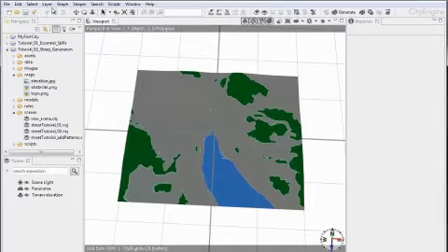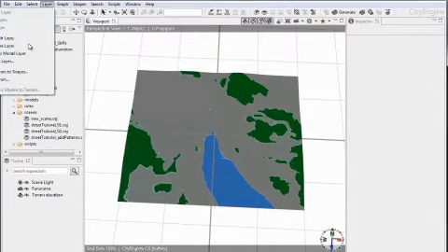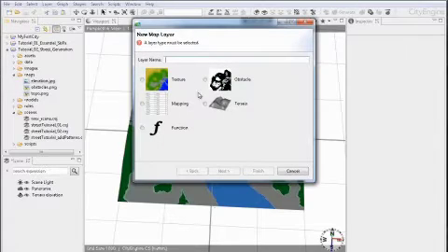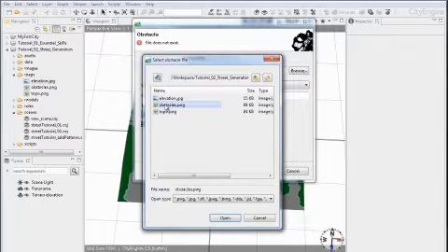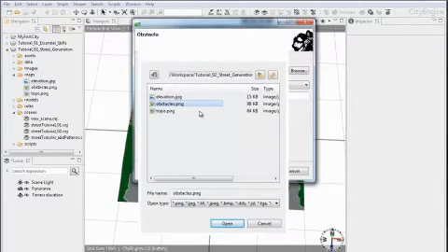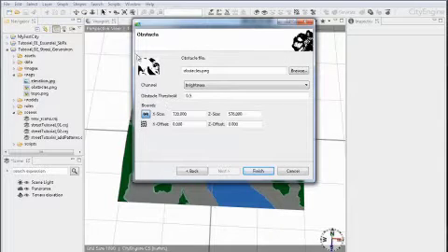It seems that it's cut off a little bit by the video, but let's just continue. New map layer and then obstacle map. And now let's go ahead and select this obstacle map here. As you will see in the preview, it is actually a black and white pixel image, and there's a threshold which can be set. So 0.5 again is the brightness. This basically tells in which regions of the city, whether in the black areas or in the white areas, streets should actually be created or not.